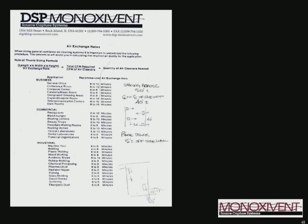Now, this is another resource for you, and this is the air exchange rates. There's a lot of information on here, but I'll just pick one as an example: if you look down, you see welding. For welding, it's 4 to 8 minutes for air exchange rate. What you do basically, there's an equation where you take the length times the width times the height of the space. You divide it by the air exchange rate, and that equals the total CFM required. Once you have the total CFM required, you can get an idea of what the unit capacity is that you're thinking about using. Then you take your total CFM required divided by the unit capacity, and that tells you how many units you will need to add to your specific design.